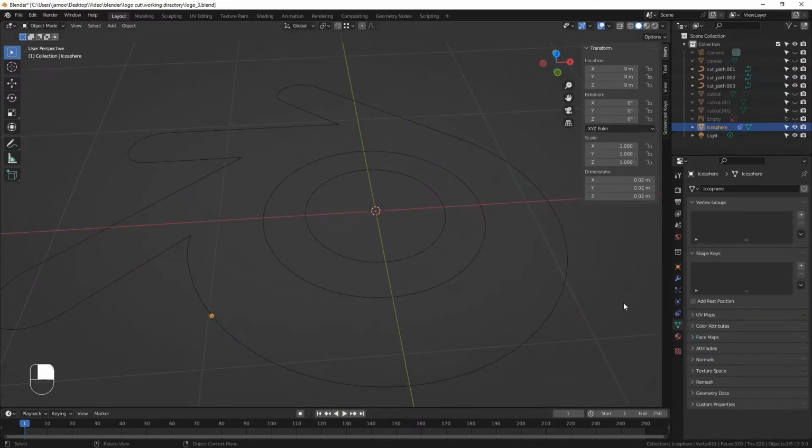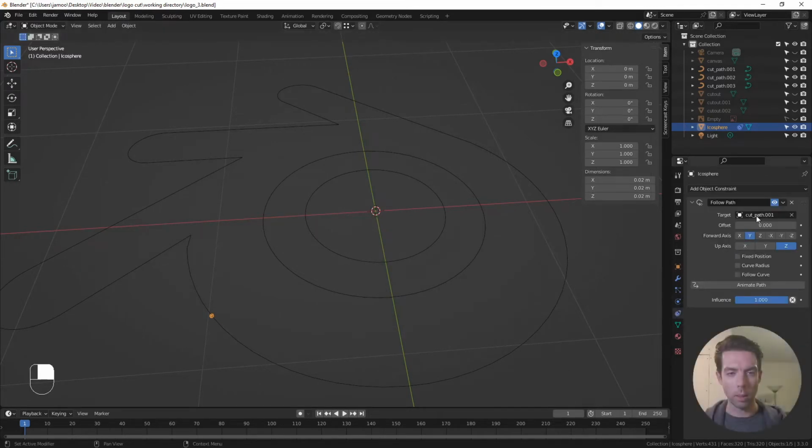So to animate this, you can see this offset, which starts at 0. We go all the way around to 100. It'll be back where it started. So I actually want this first cut tip to start up here. Because this outside path is quite a bit longer than these inner paths, I'm actually going to have 2 cut tips going around that outside path. So let's start this one. We can start this one at 50.